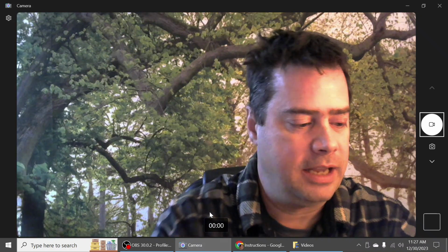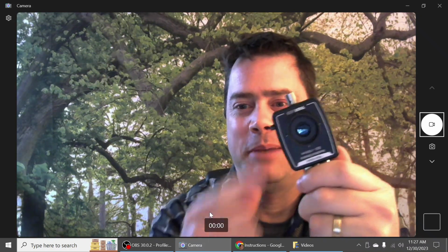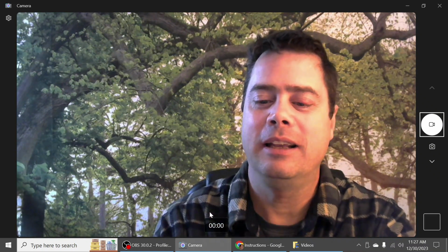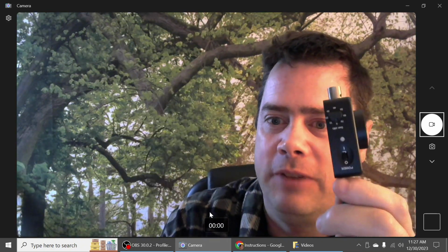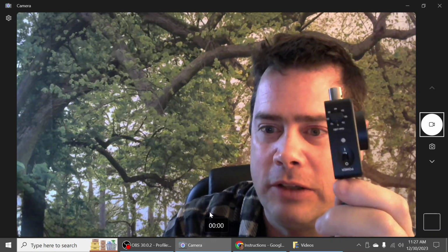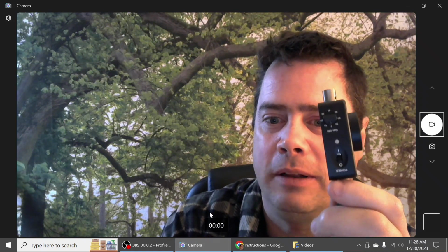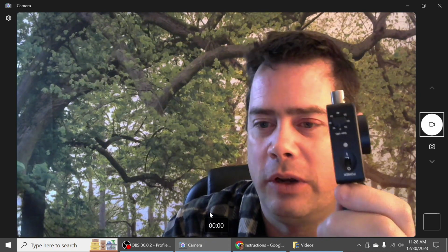And now that that's connected, there is a cap here, and of course I've lost the cap, but you need to remove the cap obviously before you take any measurements. There's also a gain switch, and that's like a zoom switch, and I have this on 0 right now. It's very important to leave that at 0 initially, because you can damage the photodetector if the gain is set too high, and I'll show you that in a bit.